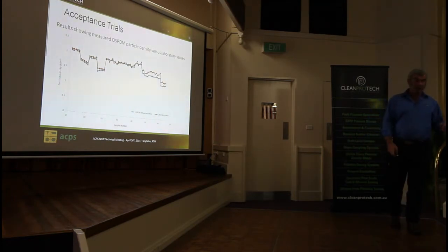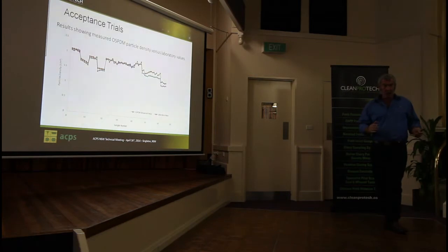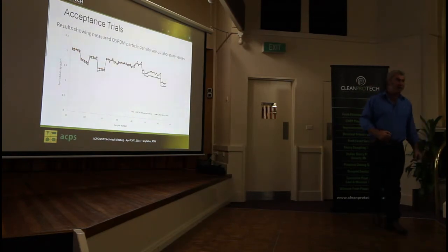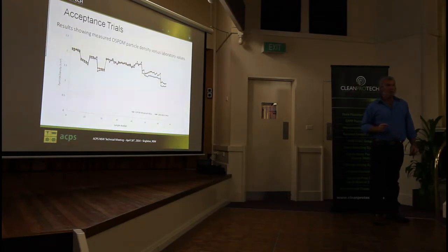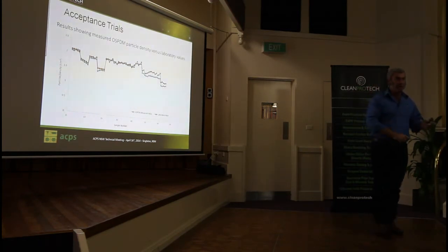And it's interesting, when we did these tests, even though Bloomfield were happy for us to do it, we went, no, we want independent verification of this. Each set of 5 samples that were taken, and they were taken over a short time period, we took samples 1 and 4 ourselves. We licensed another laboratory, Steel River Testing, Mick Campbell, and he went over our methods and agreed with them. He took samples 2 and 4, and on that we did our slurry densities, our solids concentrations and particle densities, and then sample number 3 was sent to a standard laboratory to do particle densities.